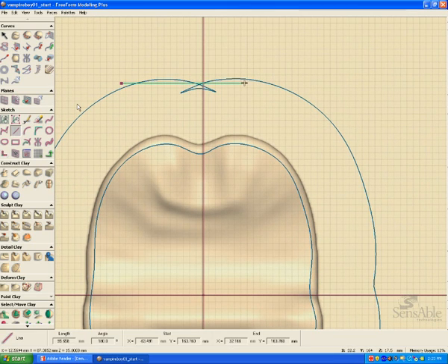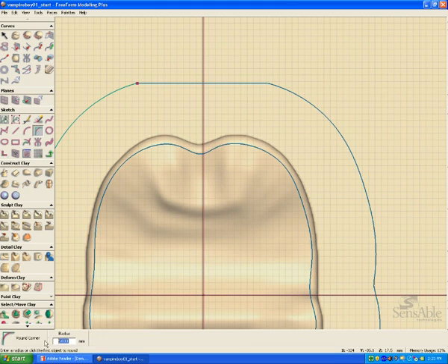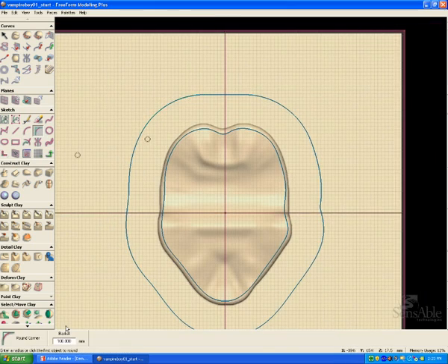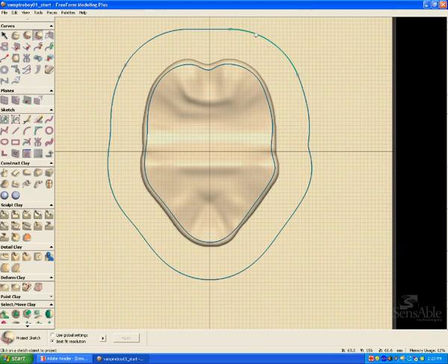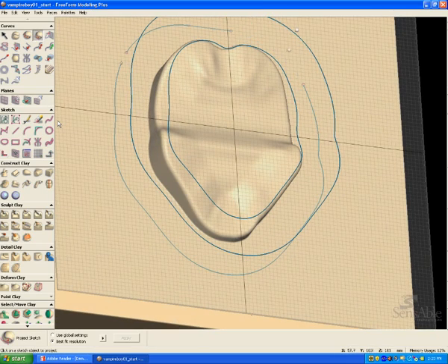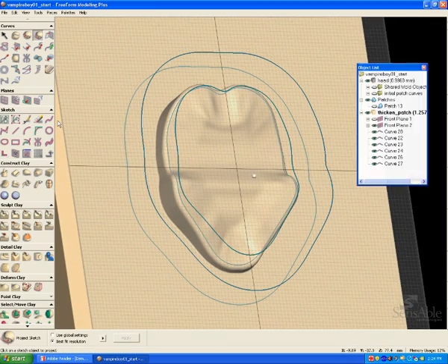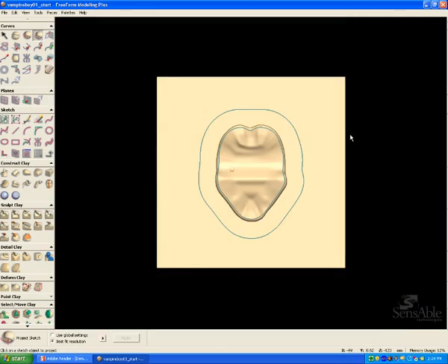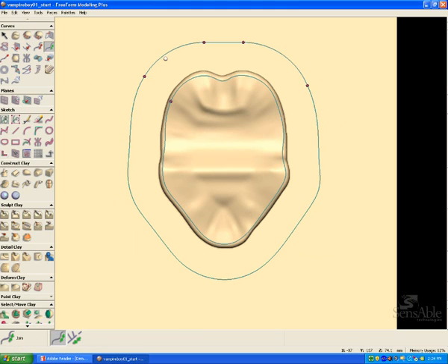it's a little larger. And once I get rid of these extra sketches at the top, as you can see, I can go ahead and use the project tool. And what I'm going to do is I'm going to take these sketches, these two-dimensional sketches, and project them into three-dimensional curves onto my clay piece. And so you can see that I now have two complex curves.